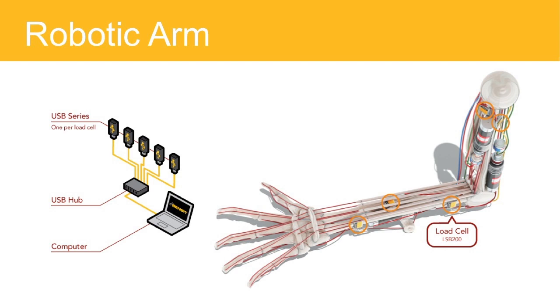In these cases, the millivolt signal is digitized immediately by the USB device, and that information is sent right to an onboard controller, normally proprietary to the end user or the builder. The slide shows the typical test and measurement array involving a PC. That would be part of the setup and programming piece of it, but at the end of the day, as you can well imagine, whether it's a full-blown humanoid robotic solution or whether it was a component such as an ankle foot, the system would be self-contained.